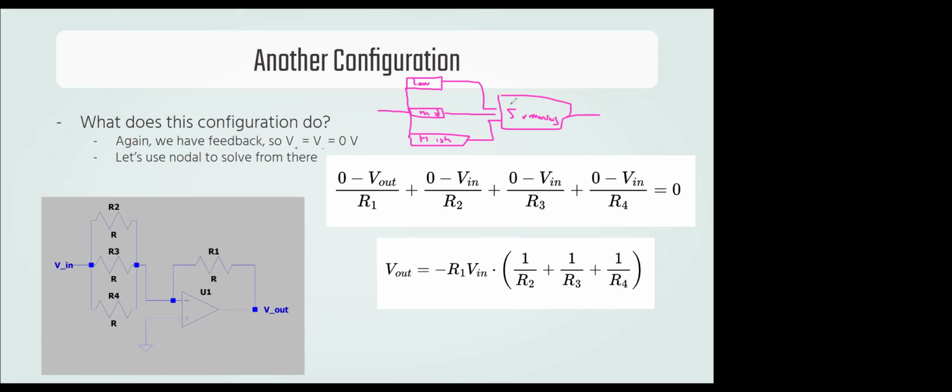And get our output. So like on the volume controls in a car, you can adjust the bass, the treble, and the mid. That's basically what it's doing. It splits the voltage into low, medium, and high with pass filters, which you didn't talk about, but those are another type of circuit that basically filter out different frequencies. And then they recombine those voltages with the summing amplifier. So, yeah.